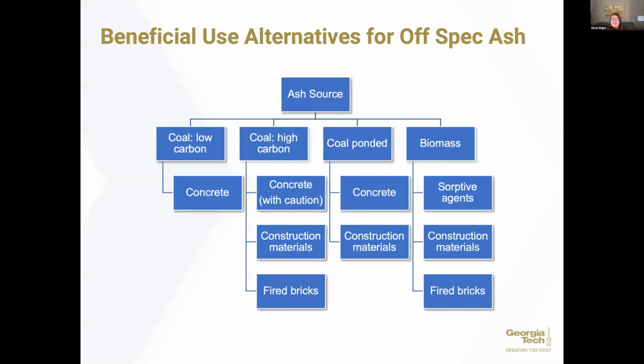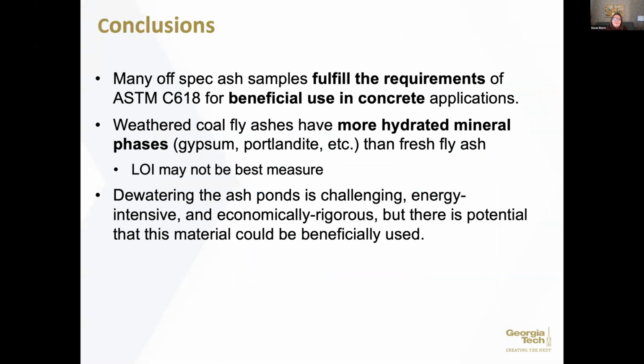Okay, so we have done tests with it as a sorptive agent. We've used it as a construction material and then in fired bricks as well. So we have other applications that we can use those biomass ashes for. So the take-home messages I want to leave you with are that many of the off-spec ashes can be used and can be used well. Weathered ashes are going to give us a different LOI result than what we see in non-weathered ashes. And we know the big challenge with using some of these ponded ashes is the dewatering, getting all that water off, because that's energy intensive.